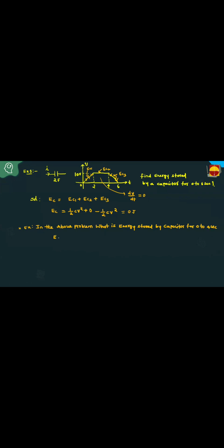The energy stored by the capacitor for 0 to 4 seconds, EC1 plus EC2. EC1 is half CV square. EC2 is 0. Half into, what is the capacitance? Capacitance is 2 farad. What is the voltage? 10. 10 square plus 0. What is the answer?